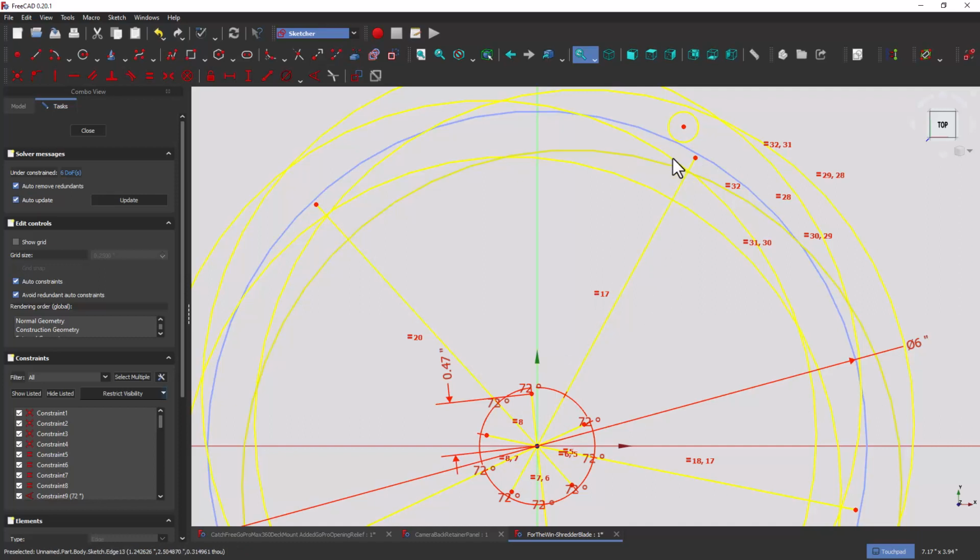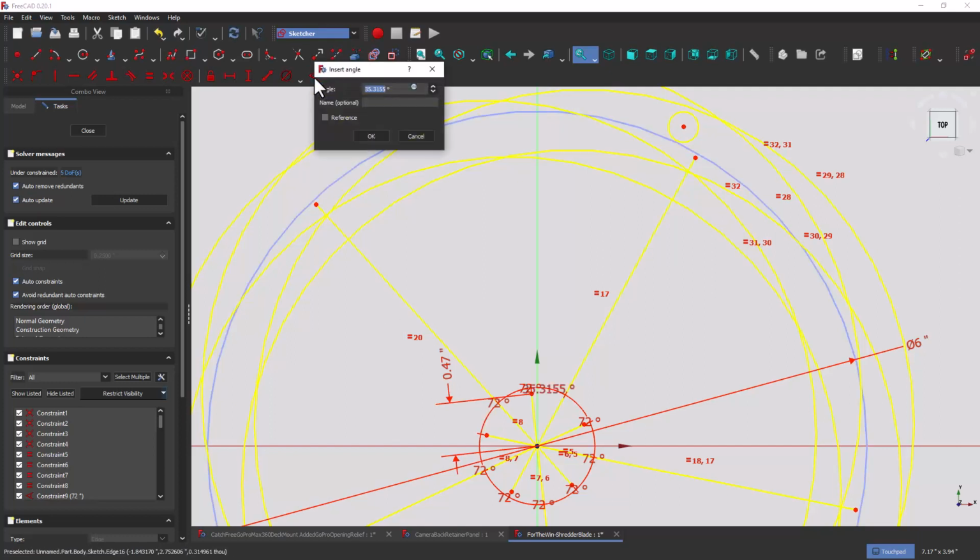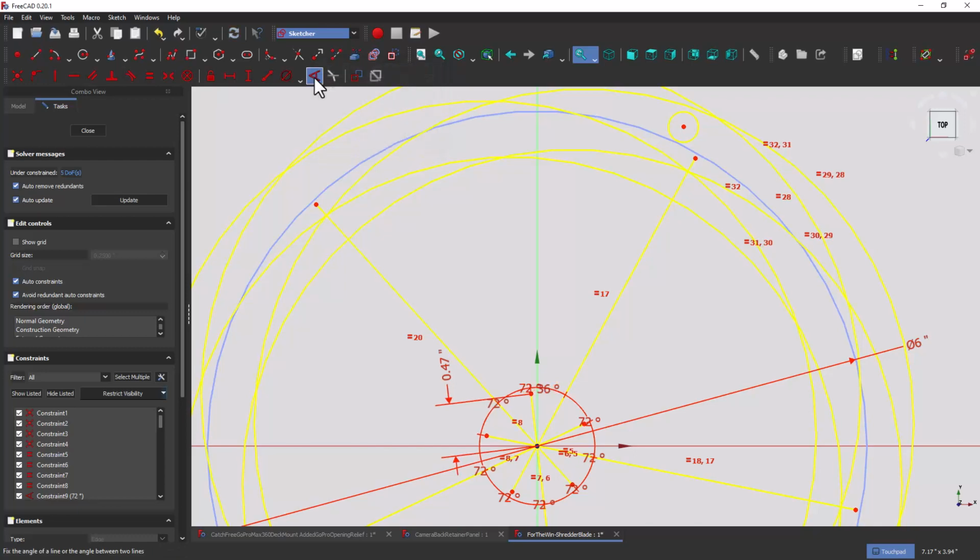Everything's nicely, evenly spaced, uniformly spaced around the center by 36 degrees now. So what we're doing is we're getting a relation of where the small circles are with the large circles. And it happens to be, say, 36 degrees. So what we're going to do is I'm going to take long spoke, short spoke, make it half of 72. It ends up right in between them, okay? So now when we move them, everything's moving. Short and long spokes are rotating, okay?